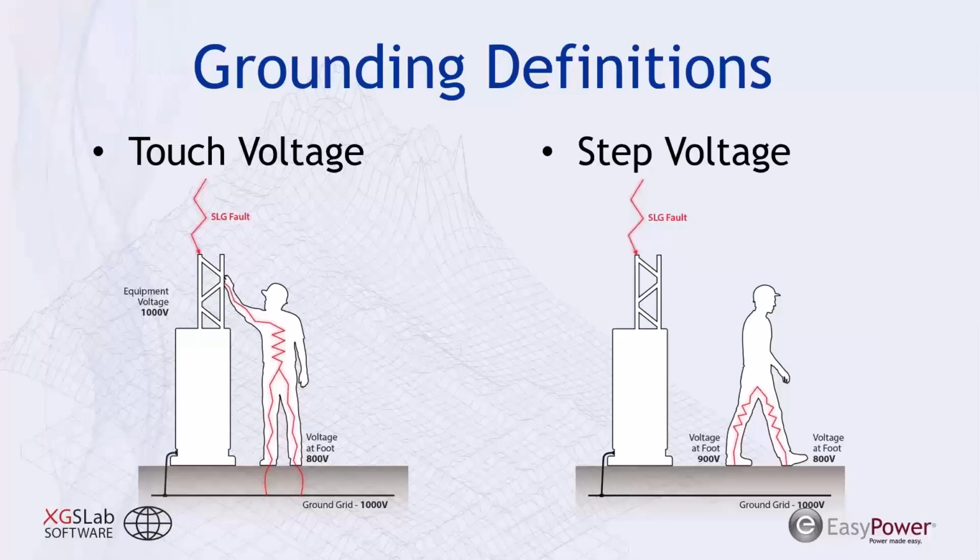And then IEEE Standard 80 is the criteria that holds the voltage thresholds for touch and step voltages. So they are highly related standards. And I do believe IEEE 2778 is also receiving comments, so it's planned to be updated probably relatively soon. Don't have a specific date or year for that yet, though.